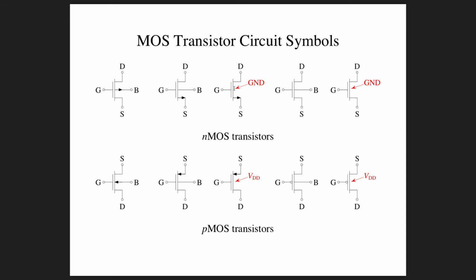On a single-ended power supply, ground is the most negative power supply voltage, and so that is the bulk connection for most NMOS transistors. So when you see a 3-terminal NMOS transistor in this class, it will be, by default, the negative power supply. For a PMOS transistor, it will be the positive power supply.